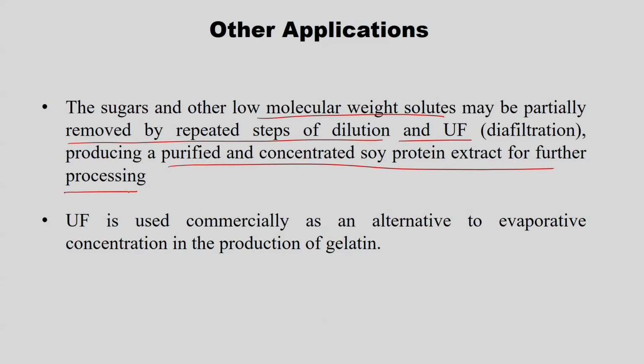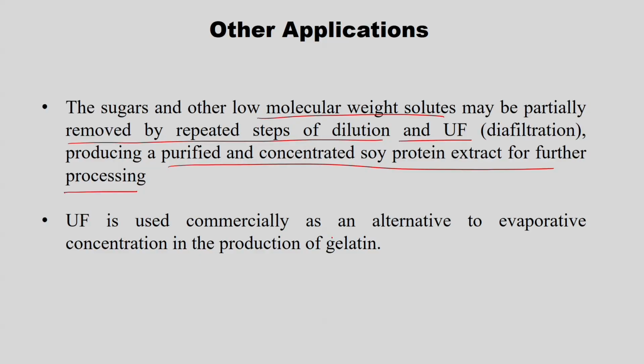So, this also can be done. Depending on what percentage of soy protein extract you want, the number of ultrafiltration modules can be added further. UF is also used commercially as an alternative to evaporative concentration in the production of gelatin. So, for gelatin production this ultrafiltration membrane is used as an alternative to evaporation.